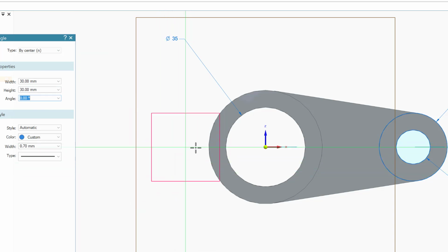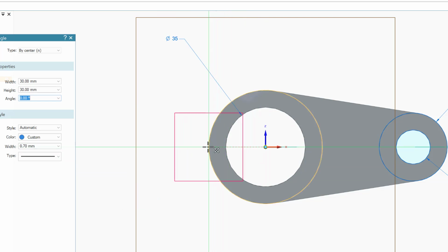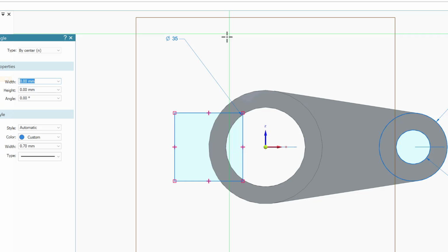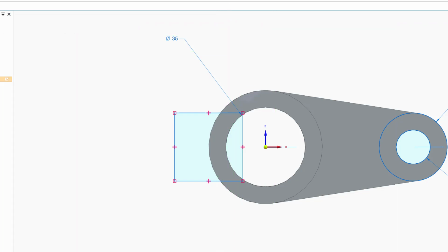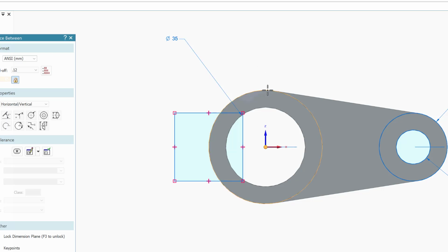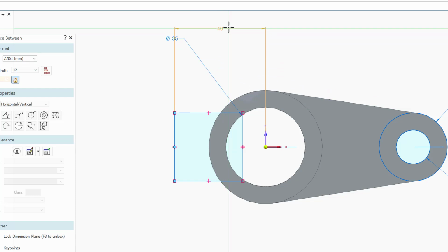See how you're going to do it. If you see here, I'm going to click with the center. I'm going to go exactly with the dashed line till I touch the tip. And where I locate the tip, you see the X. I'm going to click. This means that it will be exactly at the tip. If you want to make sure that the dimensions are correct, I can say X dimension from the center of the circle here to the edge here. This should be 40. This is exactly 40. This is exactly what I want.